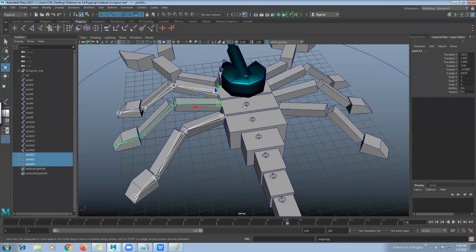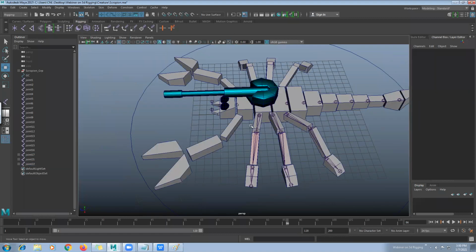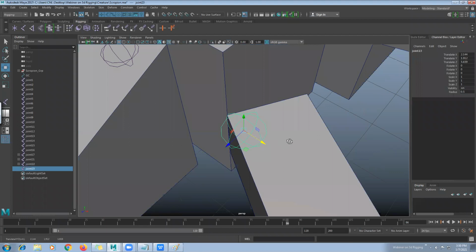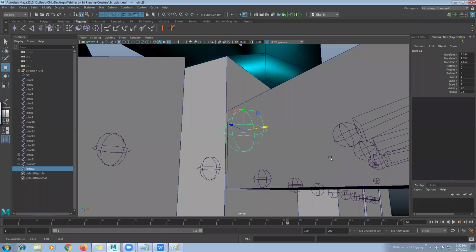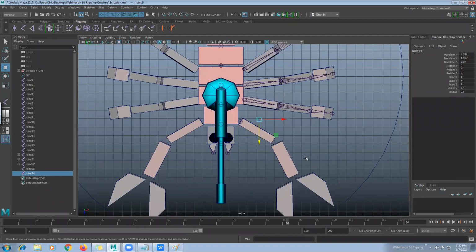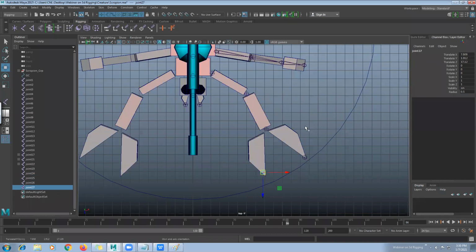Again, we can take a copy of it with Shift D, drag it out and place it the proper way. Shift D, go to the top view, drag it out. Again, do the same thing. Shift D, again put it here. Now again check from the front axis.